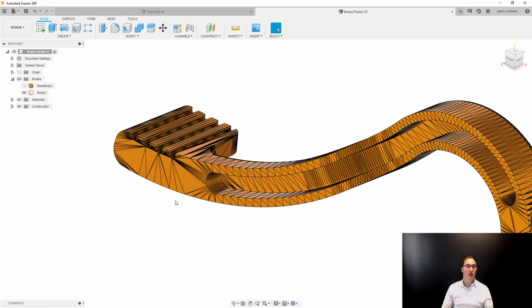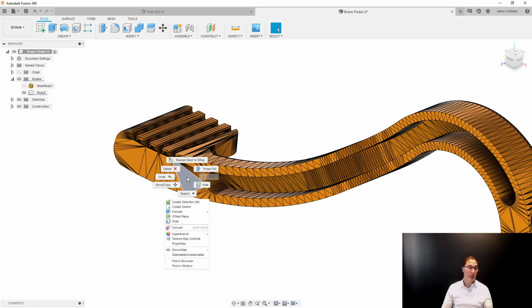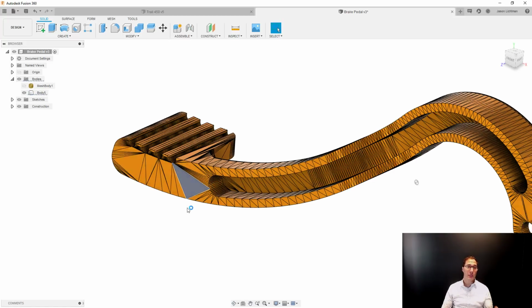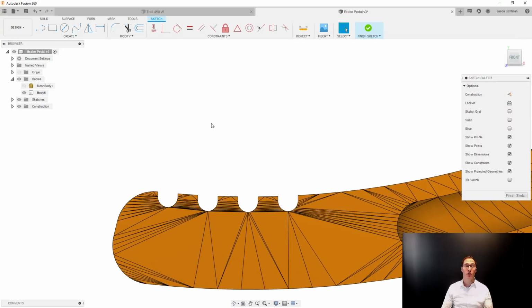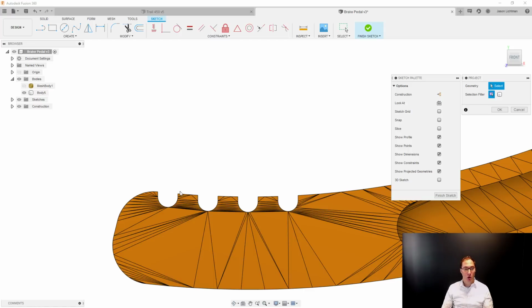If you look over here at this face, this triangle, and this one here, oh, by the way, now that it's a BREP, I could actually select individual triangles, also edges, and also vertices, however much I want. That means that I can create sketches. Let's actually go and do that real quick. I can create a sketch and I could project geometry from other vertices that I already have here. So I'm hitting P for project, and I'm going to project a couple of these points on this face over here. And we'll grab maybe this one over there too.